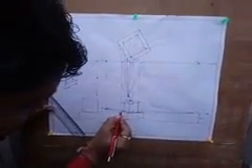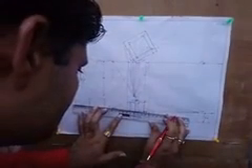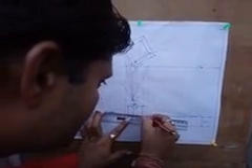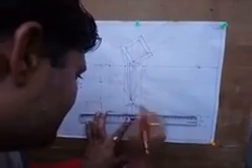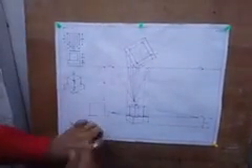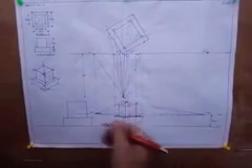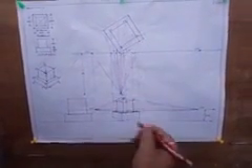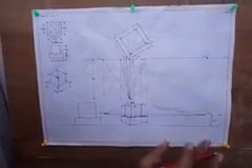Now the remaining lines are to be made dark. This is the vanishing point and this is the edge. Now this is to be darkened. Here is the point and this is the vanishing point to the right. Here it is to be darkened. Now this is the total perspective of this object. The back point is not to be shown, or the edges which are to the backward side need not be darkened. Okay, so thank you.